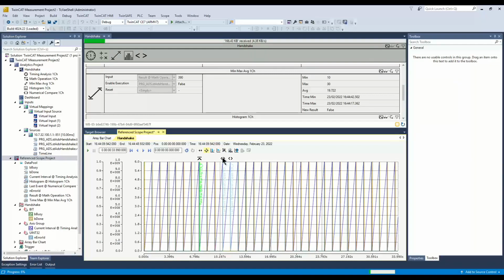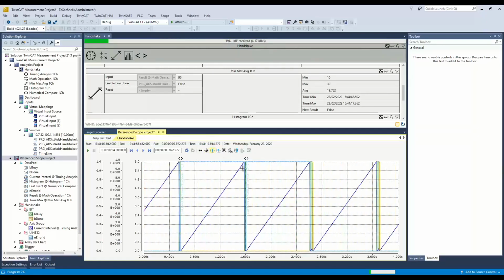So here at this position, I see there are 2 trigger elements integrated, and this was the scenario where I simulated this error situation. I can see the error was happening at this position, and you can also click on your error ID value. I see the error value 6, so that means, for the well-known users of ADS, it's a target port not found. It's just this situation that I simulated at the moment when this appears.